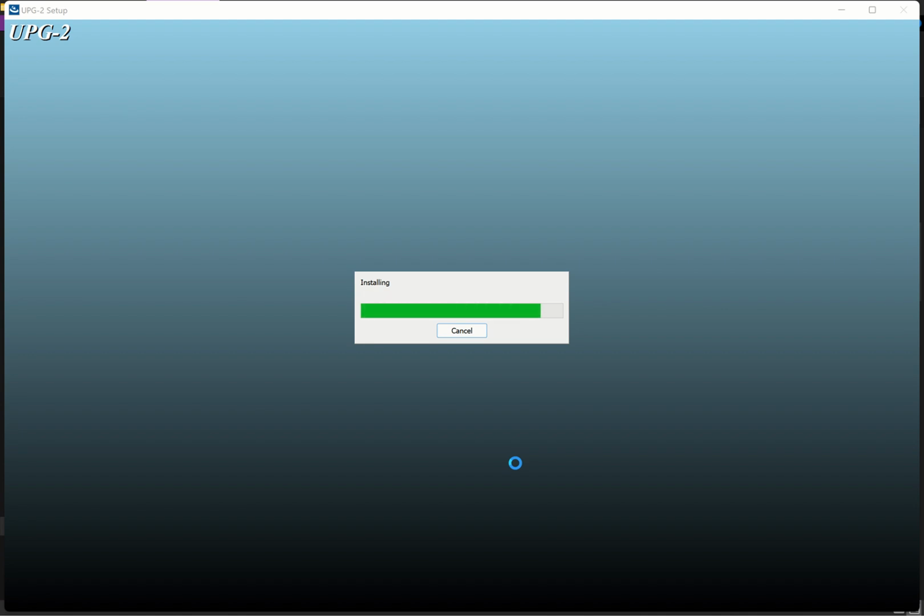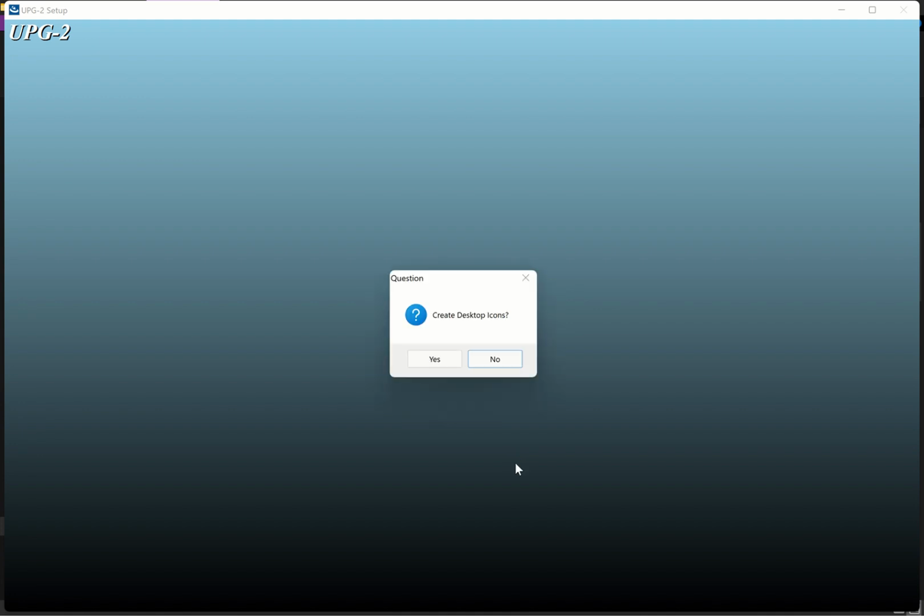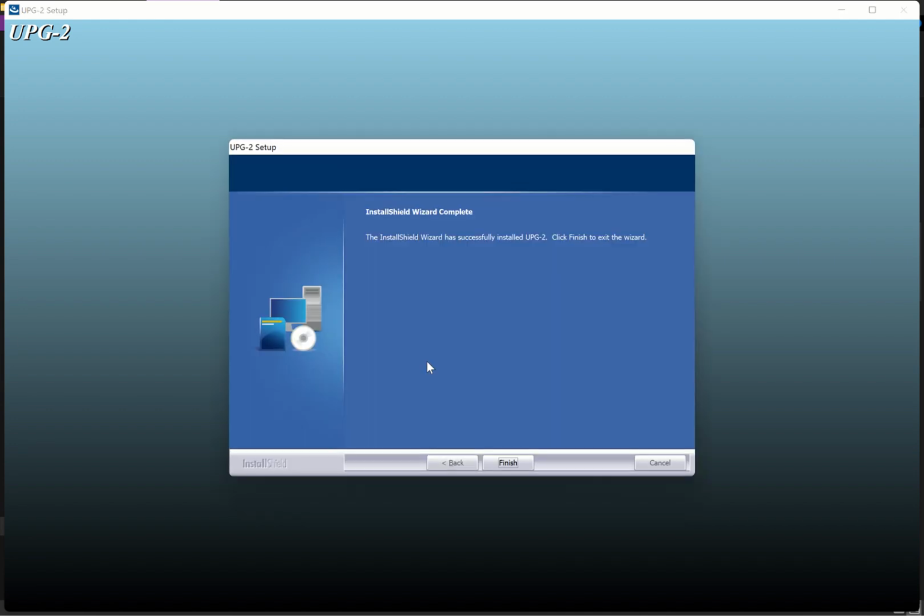So there are many ways you can access a post processor for your machine. SolidWorks CAM uses .cps, but Fusion 360 and HSM use .ctl. So you need to understand how to convert CPS to CTL, and say yes. Did it finish? I want to see how it will work for our case, if it will work for our case or not.